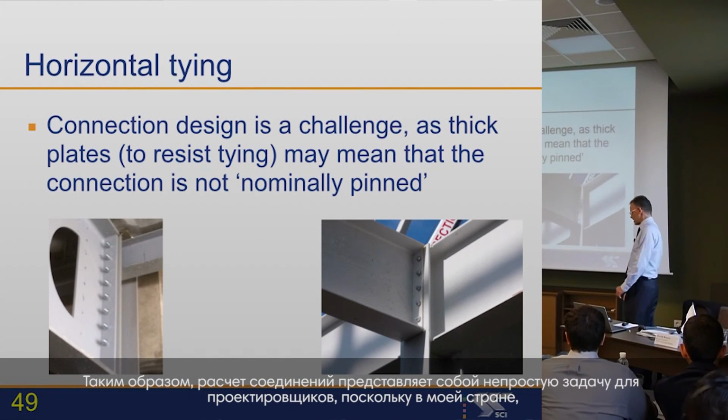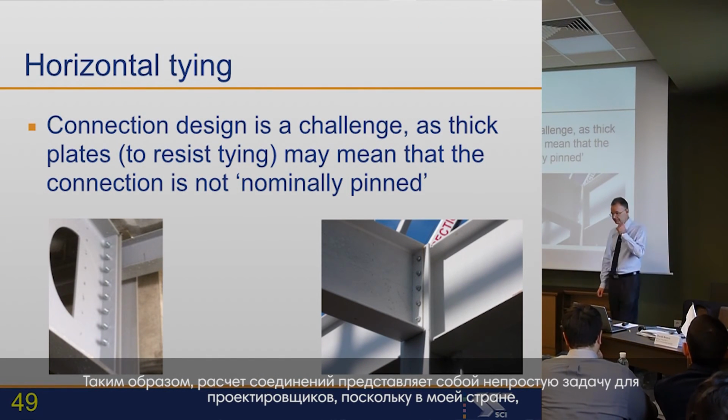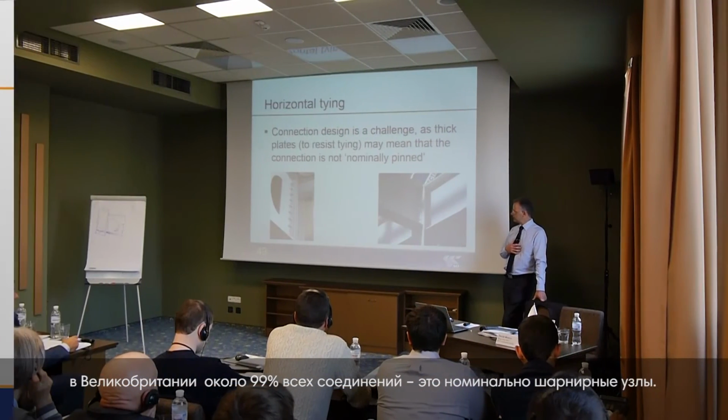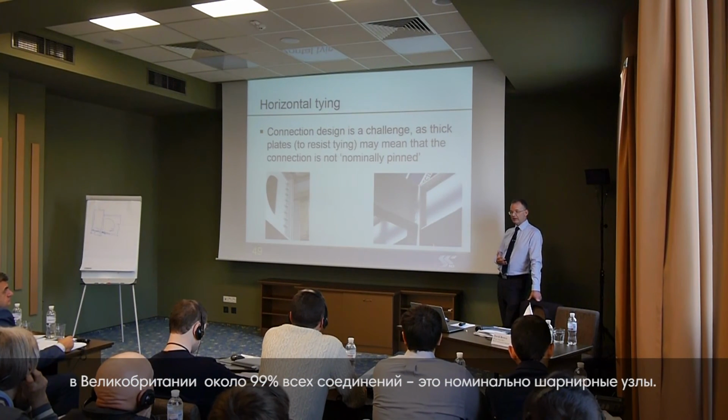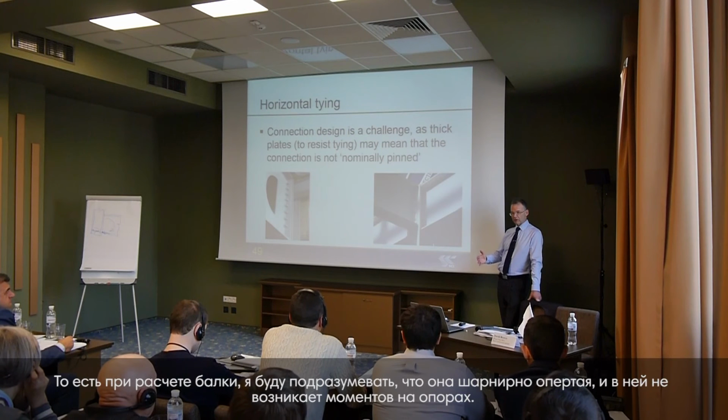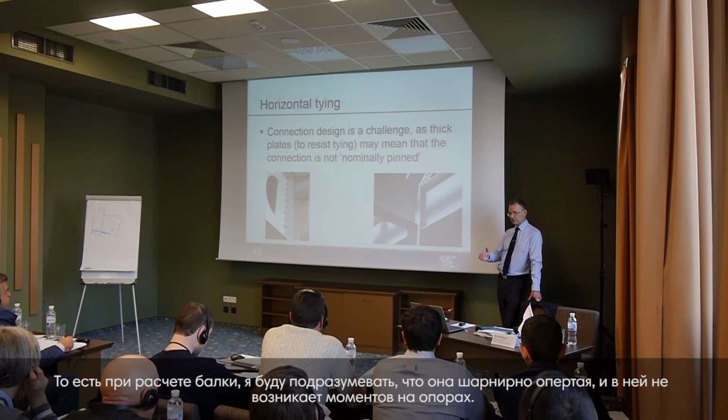So there is a challenge then to connection designers, because in my world, in the UK, 99% of my connections would be nominally pinned connections. So I would be designing the beam to assume that the beam is simply supported, carrying no moment at the end connection.